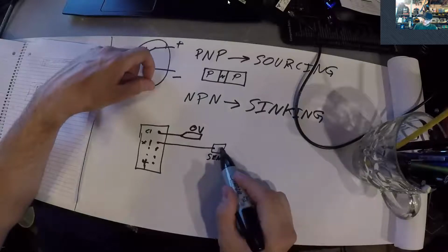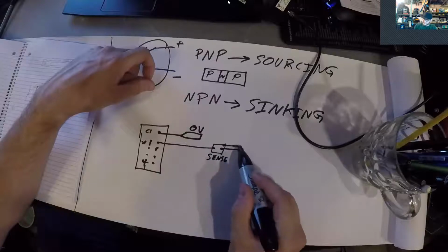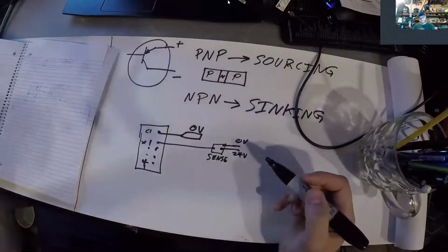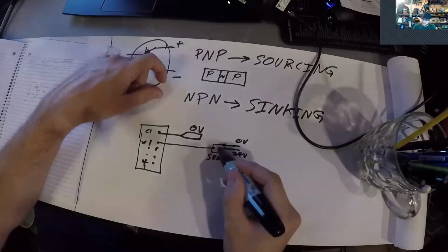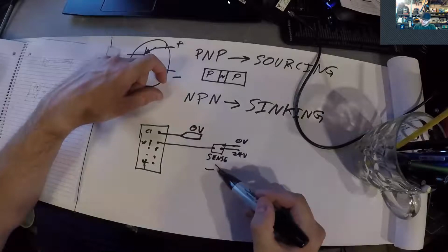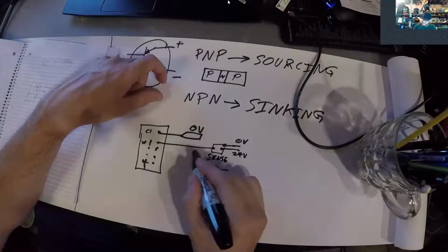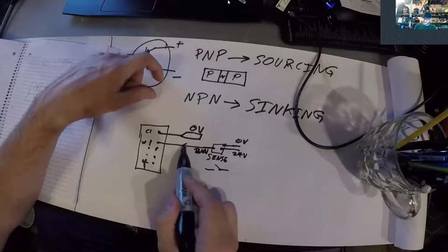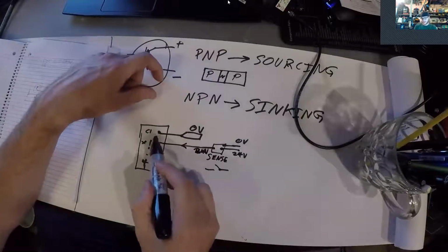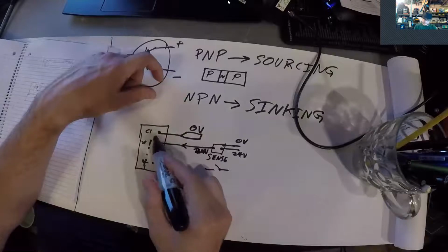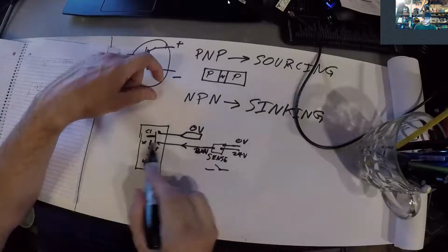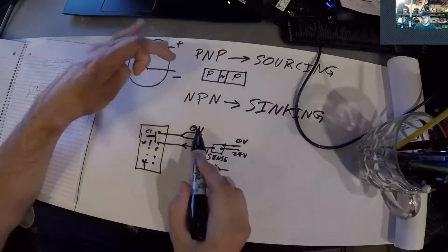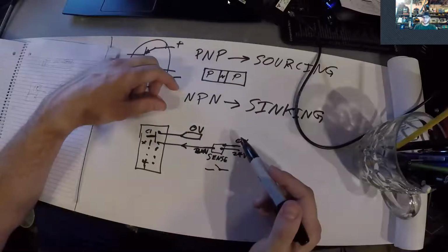and then that sensor also gets 24 volts and 0 volts. But basically, internally, this sensor has a switch, and when that switch closes, it puts 24 volts out on this line into the controller, and then inside the controller, there's basically a switch that gets closed, and that sinks down to your 0 volts, which is essentially your ground in this circuit, right?